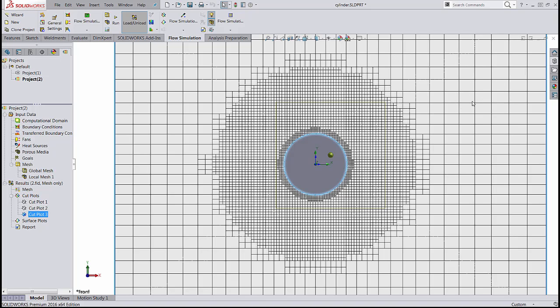In terms of when and where to use this, it's important to note that if you have fluid around a car that you're trying to simulate, where there is more changes in important parameters like pressure and velocity after the car itself, where there's more turbulence as compared to before, you would notice that having a dense mesh before your fluid hits the part itself is not useful in giving you better results. It just increases the amount of computation